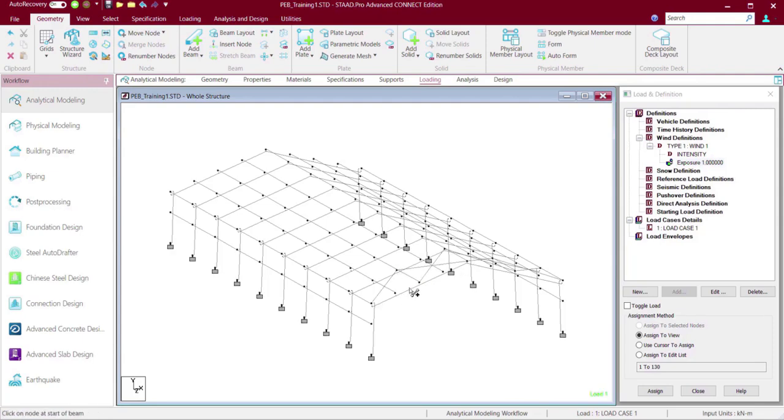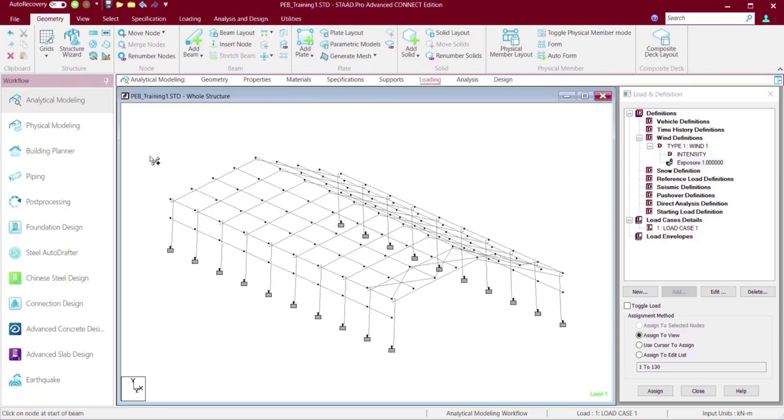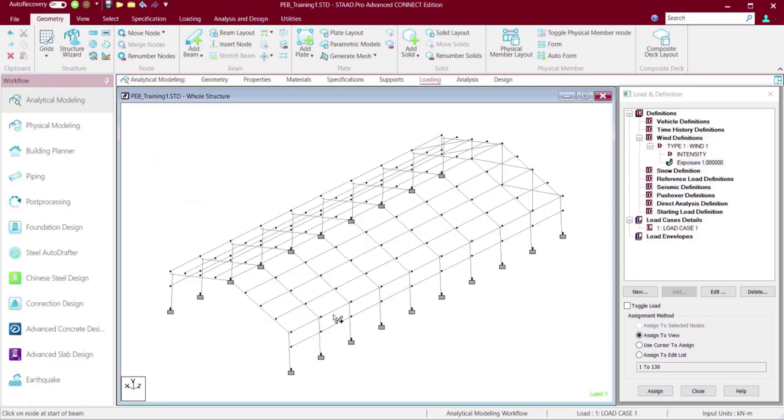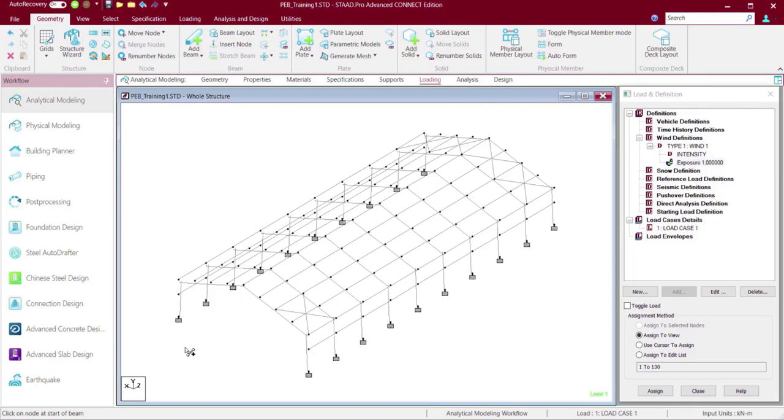That's because the building is not having any kind of diagonal bracings on the horizontal planes. So we can apply some diagonal bracings on those roofs so that the building has significant stiffness against the rotational activity. Next, we'll assign the bracings on the vertical frames.